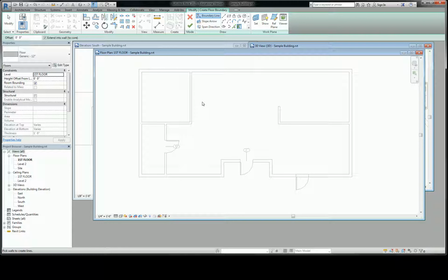That level of detail frequently is modeled into Revit. Like what you see in your plan is this to this, but you're actually going to align it to the inside edge. In this case, since we're working with generic models, we're going to take that slab. It's going to look just like a straight slab like that, and we're just going to take our mass right down to the edge. Okay, does that make sense?